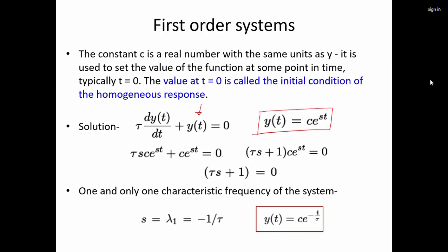You are measuring the pressure of a chamber and suddenly there is a change in pressure. How quickly is your manometer or pressure transducer able to measure this changed pressure? So these are the dynamic, time dependent characteristics. In order to understand those, when we talk about temperature and pressure measurement in detail, knowledge of orders of system is very important.